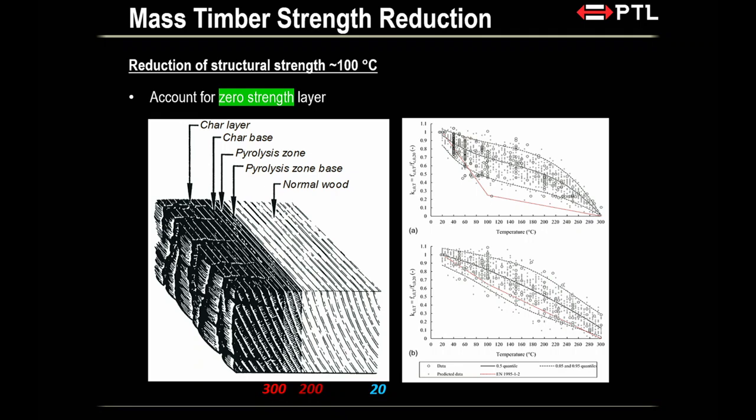Of course, you might have to live with less exposed timber, but again, a lot of decisions, a lot of conversation to be had. Now, my last worry, structural strength reduction. In fact, maybe you guys can tell me more about this, because you would have probably seen these strength curves before. The structural strength of timber reduces quite significantly at about 100 degrees Celsius.